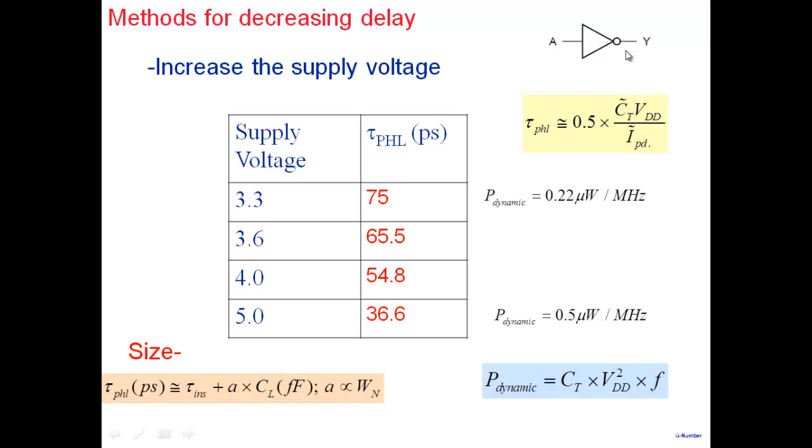So in this case, it helps, as I said, if this is a significant component of delay, extrinsic delay, increasing the size of the transistor will cause a reduction in this particular term. A will be inversely proportional to Wn, not directly proportional. So as you increase the size of the NMOS, the delay value will decrease. And as I said, first order approximation, the intrinsic values will remain the same. But there's a problem with it. Focusing on this inverter, increasing its size will reduce the delay.